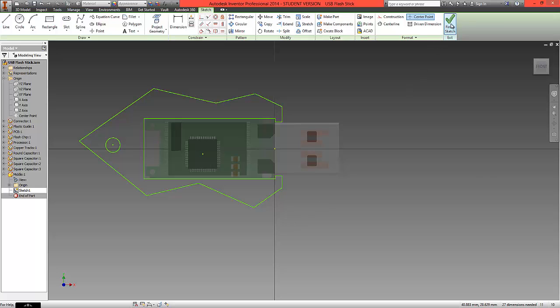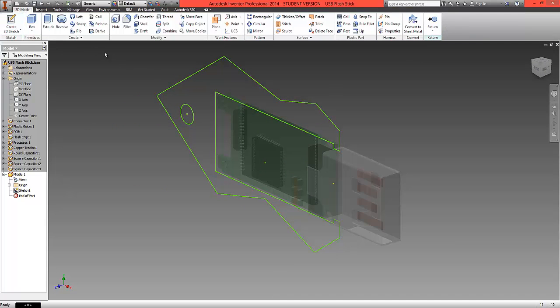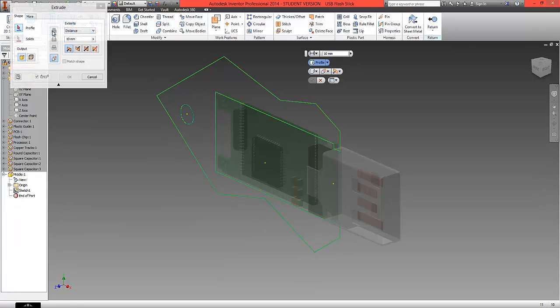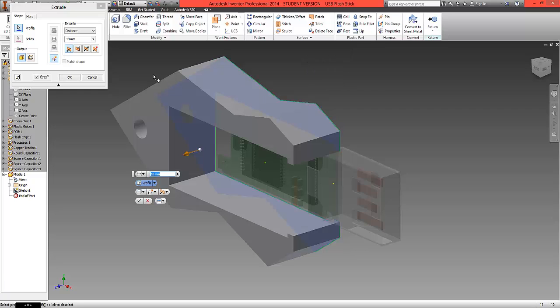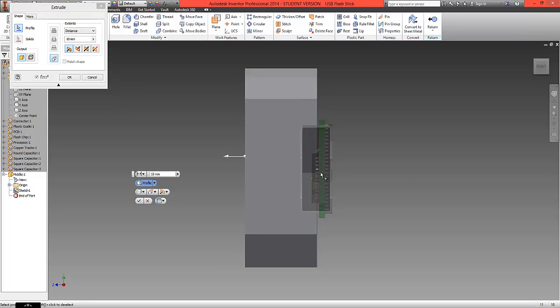Finish the sketch using the top option of finish sketch, and if we now choose to extrude, we will see that we can select this line work and we can see an extrusion. What I'm going to do here is use the view cube and click on this surface of the view cube here to see how far I'm projecting this geometry.